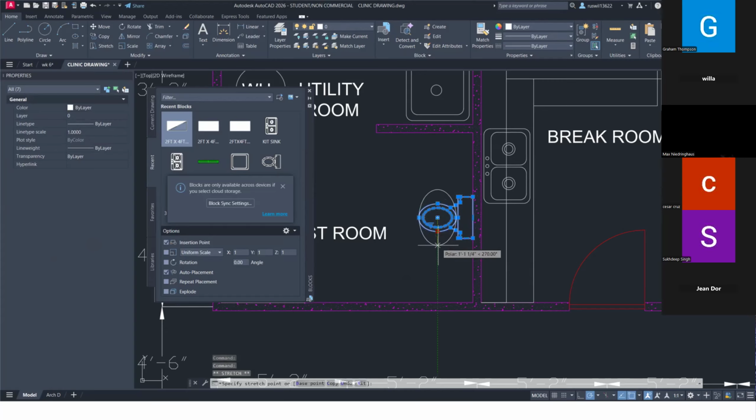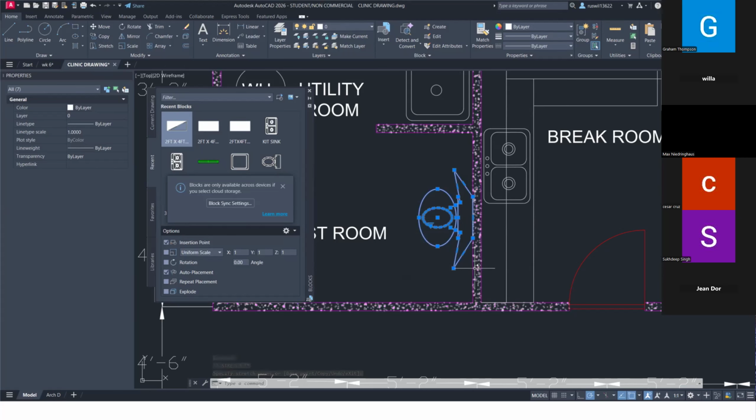Maybe you tried to move it and grabbed that circle. Go ahead and do that. That's fine. We'll go back a step. Instead of moving your block over 3 inches like he was trying to, you accidentally change the shape of the block. When you're dealing with individual geometry, it can get a little funky if it's not all locked together.